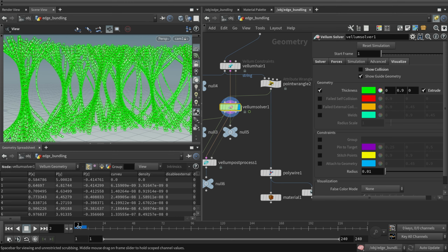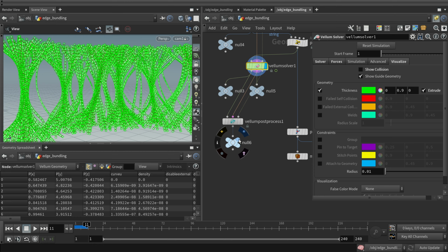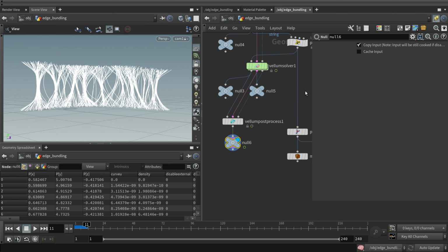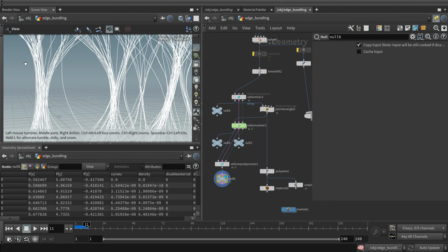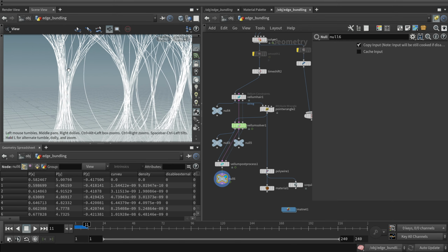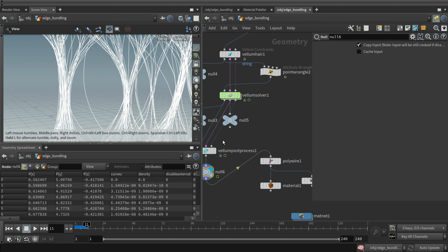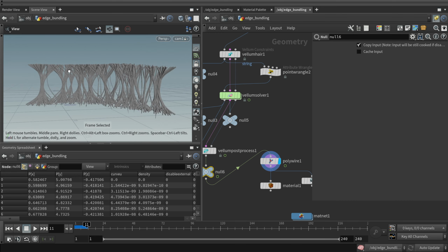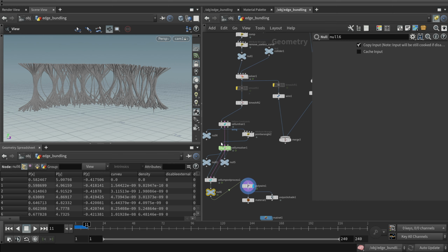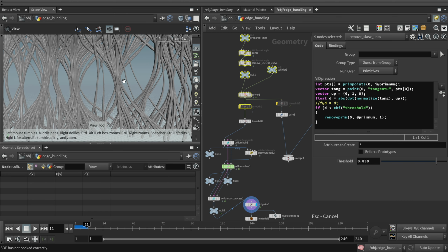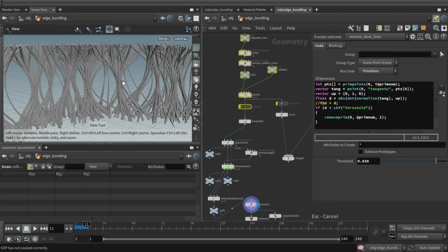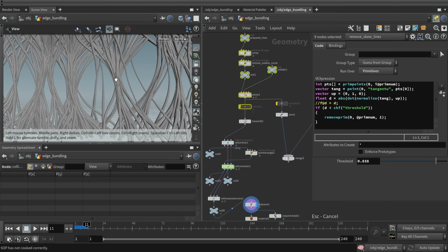Alright, let's see. It tries to detangle itself, and then I just smooth it a little bit by using the Vellum post process. So we got this. This is before and after. But actually, it's very hard to completely detangle the self-collision, because they are basically just overlapping each other. So I think we should solve this problem inside the Vellum instead of inside the sub-solver. But you should put it into Vellum only if you try to design this kind of tube structure.